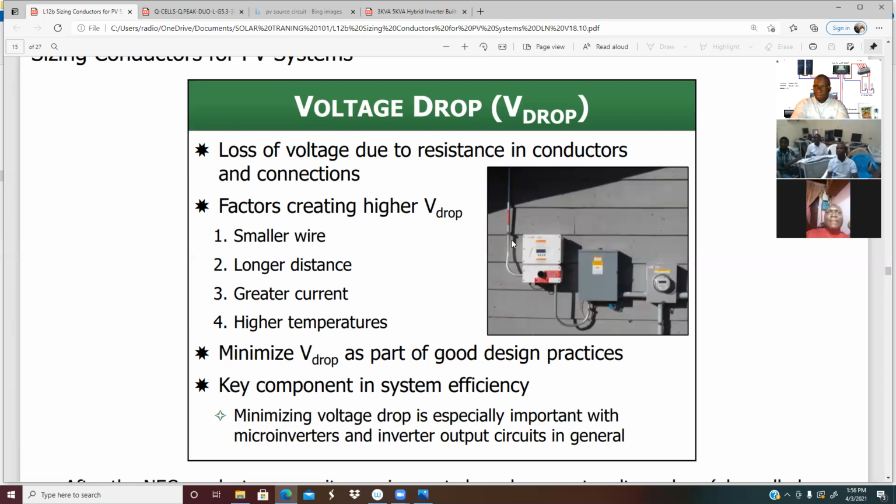After doing the sizing, if you want to add amps or add volts, you have a calculation to do. This calculation tells you exactly the size of wire to use in that configuration, so that you do not lose more than 5%, because in any installation you lose some voltage.